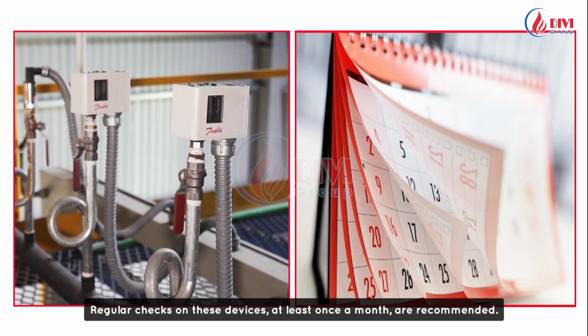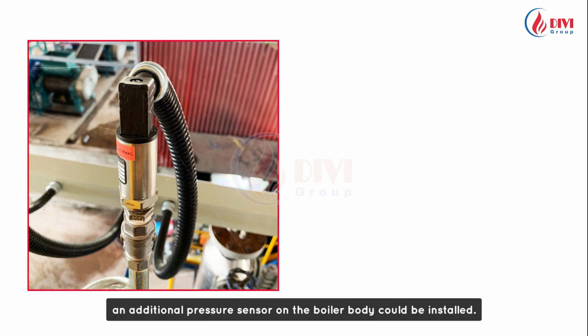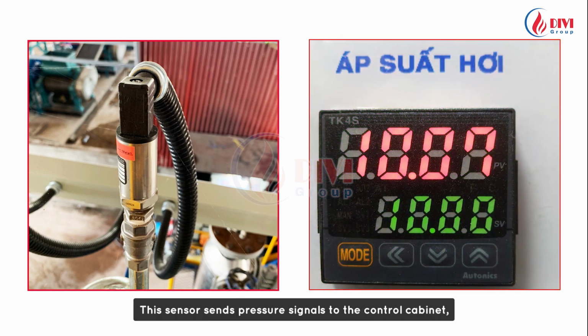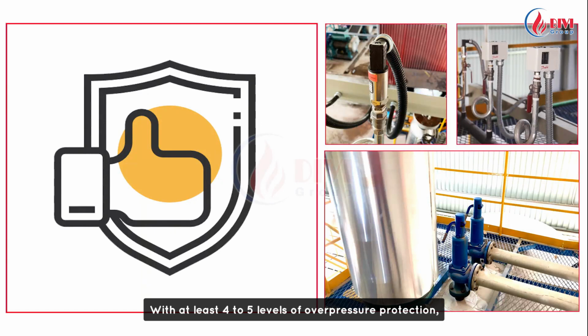Regular checks on these devices, at least once a month, are recommended. For further safety, an additional pressure sensor on the boiler body could be installed. This sensor sends pressure signals to the control cabinet, where protection modes are set up. With at least 4 to 5 levels of overpressure protection, the boiler's safety against overpressure is nearly absolute.